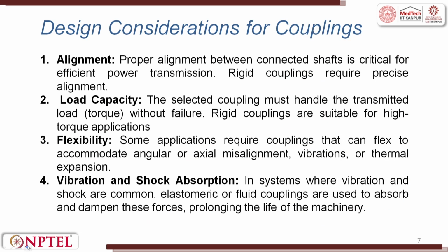Next comes design considerations in couplings. First and the foremost thing is alignment. Proper alignment between connected shafts is critical for efficient power transmission. Rigid couplings require precise alignment, while flexible couplings can accommodate some or slight misalignment.